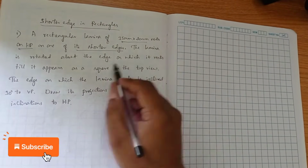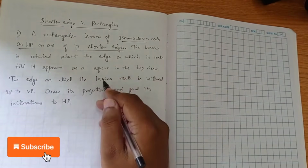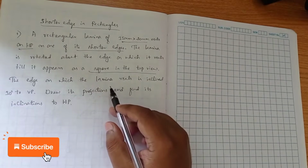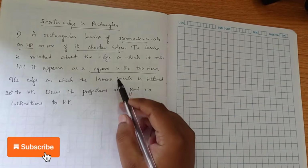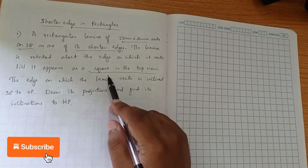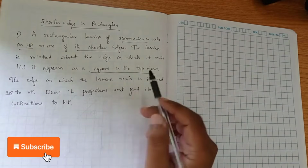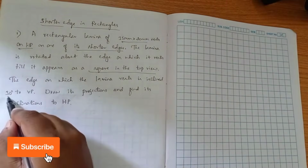Now the lamina is rotated about the edge on which it rests till it appears as a square in the top view. So it is similar to your isosceles triangular problem, wherein the second position is an equilateral triangle. Here they have not mentioned the angle of inclination to HP. Instead, they have mentioned the second position top view, in which we get a square of dimension 20. Now the edge on which the lamina rests is inclined to VP at 30 degrees.